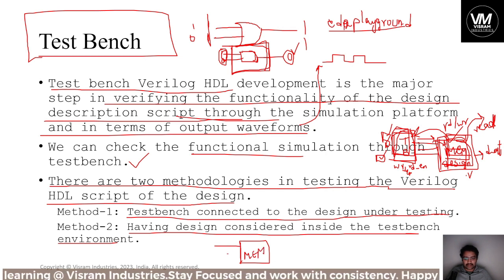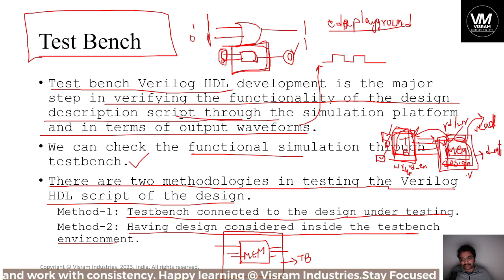Now these input wires and output registers are all considered in a closed environment of the test bench. That is the most ideal case of using the same design inside the test bench environment. In the test bench environment, in a universal way, we have all these input wires and output data collections, and whatever hardware you collect here can be brought into this test bench environment and tested in it.